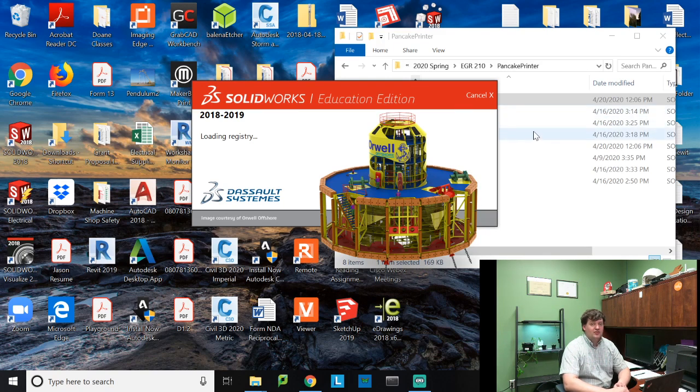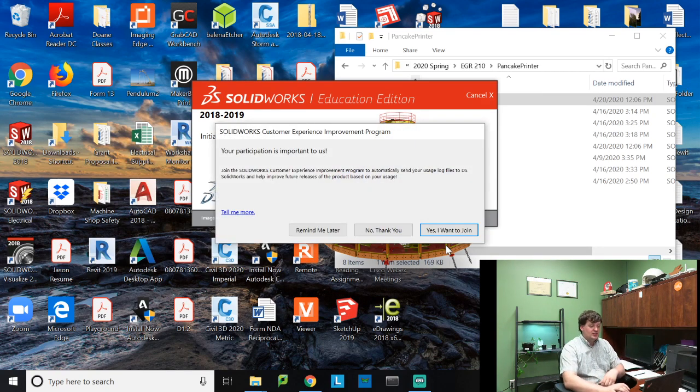Again, remember, if you wanted to just send me this assembly file, you would have to send me every single part file in the assembly, and every single assembly file that's also in that assembly. This is why you need to organize your files. I have this saved nicely into one single folder. The reason is that if I need to make any edits or make a version 2.0, I can go back in and edit these files, but I can keep them all together.